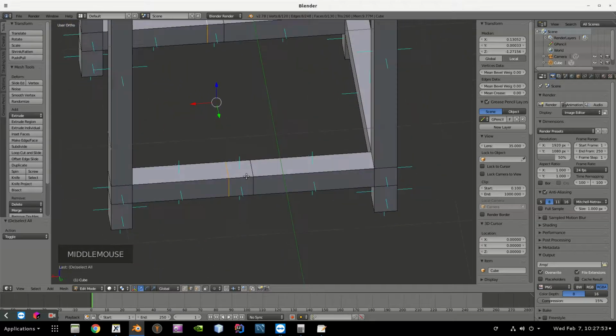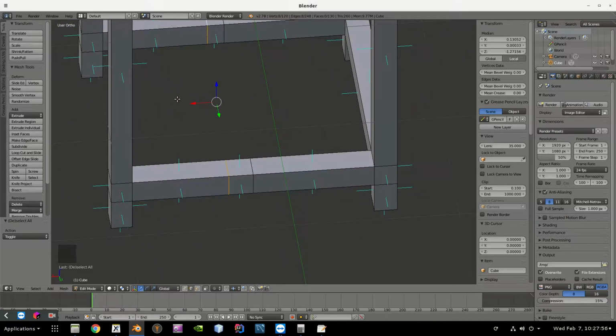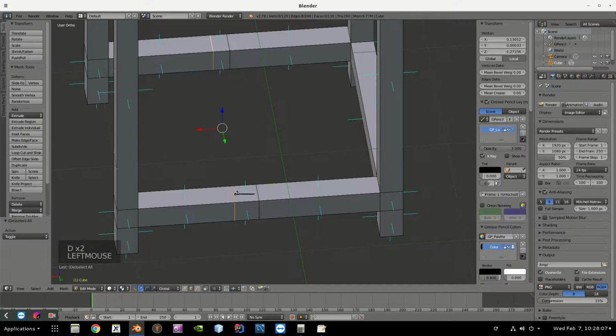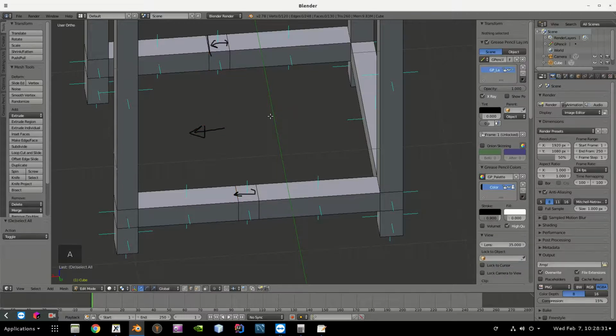Okay. So what I want to do now is I want to align them on the x-axis. Any guess what I'm going to do here? See, the problem right now is this is wider compared to this. I want to bring them together on the same line. What should I do? S? SX0, because this is happening on the x-axis. SX0. See, they move together, and now this is right.